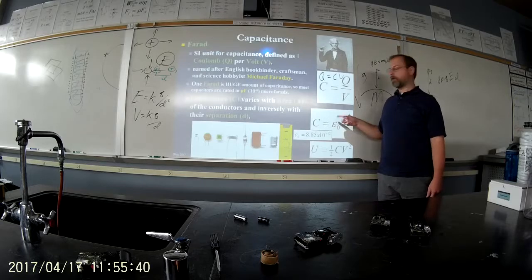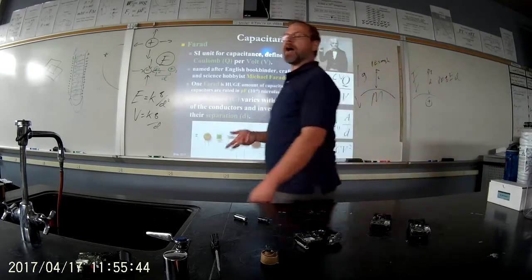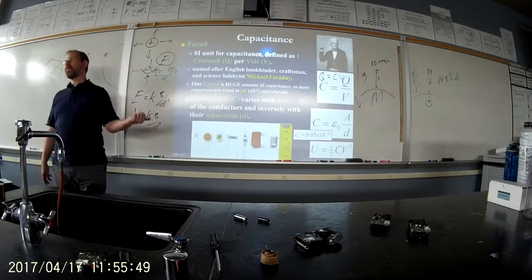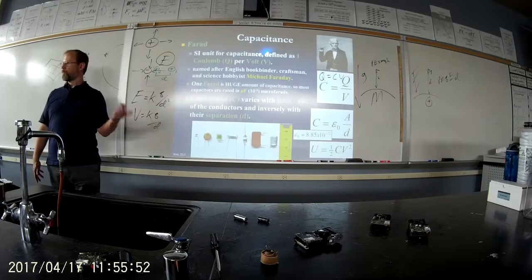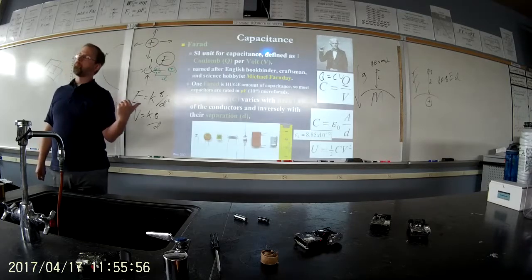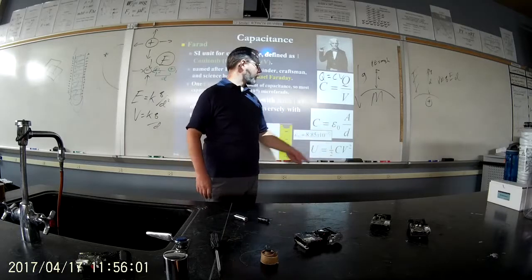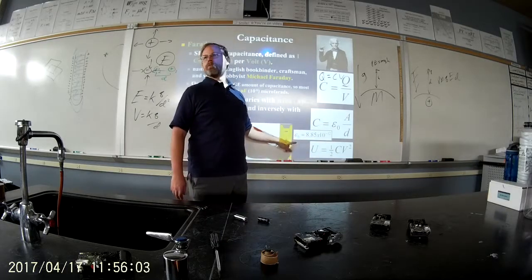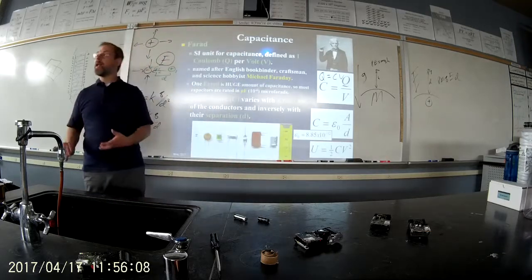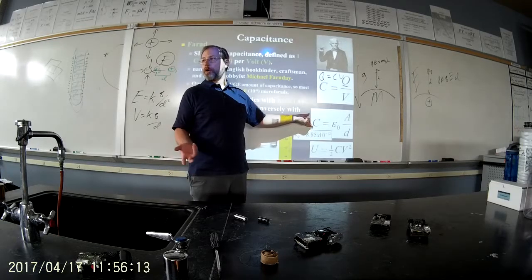The epsilon here, that is a little epsilon, is a representation of the strength of the dielectric. That's called the vacuum permittivity of space. That's the dielectric when all you have is air. Metal, air, metal. Most dielectrics are vastly superior to that, but that's the formula. Epsilon naught is the dielectric for air. You might have like epsilon plastic, if you just use plastic. So the better your dielectric, the higher your capacitance will be, the more charge you can store.